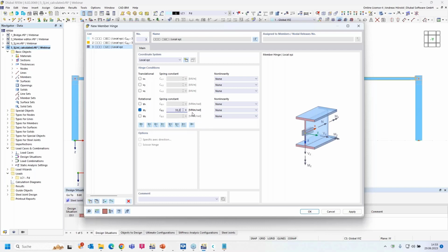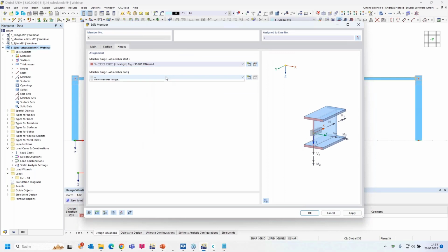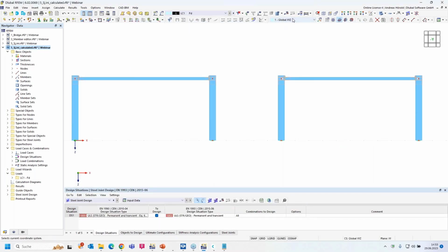The default setting is kilonewton meter per rad, and I changed it previously so that I can compare the entries better with the DSTV guide. Okay, the beginning and the end. So let's calculate all.